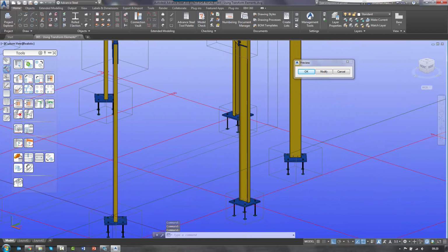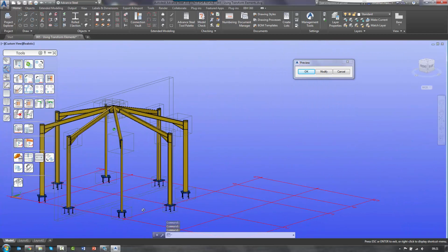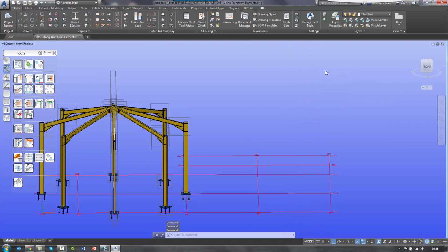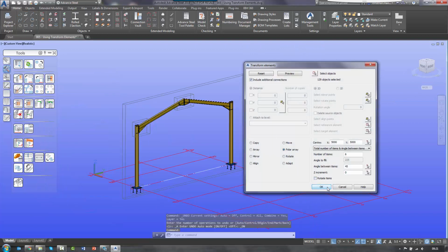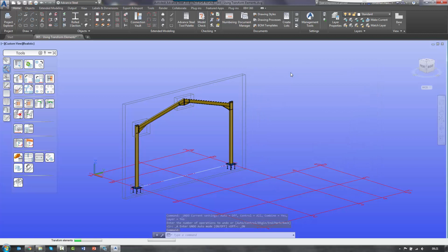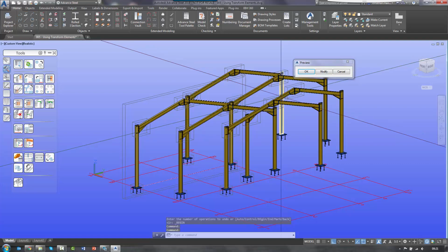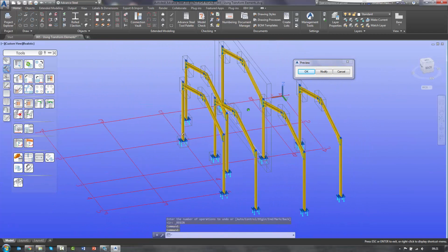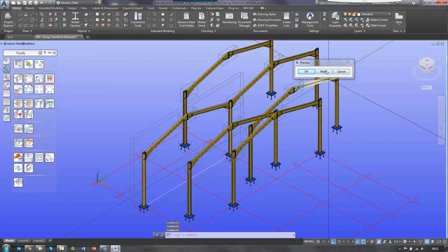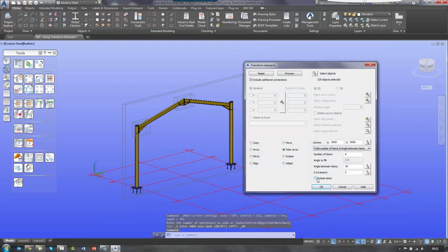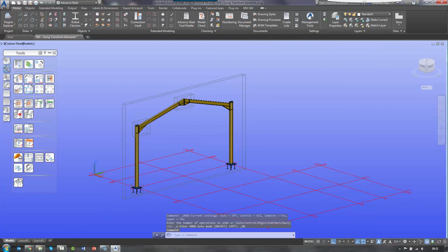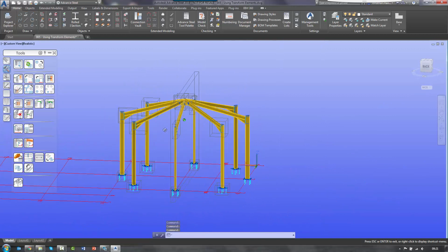You will see when the rotate object tool is on, the objects and columns rotate around that angle. But if I modify it and I say the rotate items is off, then preview it, you will see that the objects do not rotate. So again, if I go to modify, we want to ensure rotate items is on, click OK. And then we can form the objects like that.